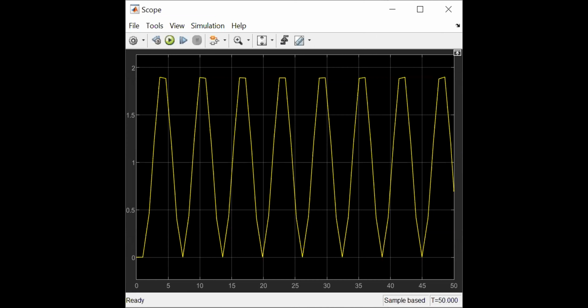And here, what you want to do is select fixed step, and then it will ask you for solver details, solver step size, and you can play with the parameters over here. Say, for an example, you can say this is 0.01 and click OK. And then go back to your screen.